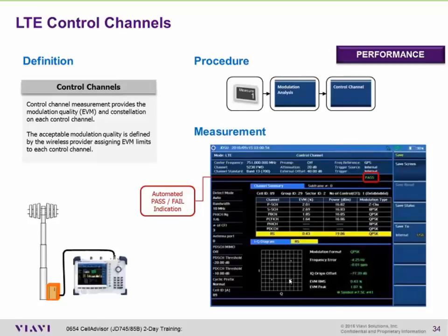Unfortunately, the physical spacing between these antenna elements, because they were inside of an enclosure, was actually degrading the modulation quality when they were both transmitting. So we had actually isolated the failure to an antenna enclosure through signal analysis and using our instrument. So bear that in mind.